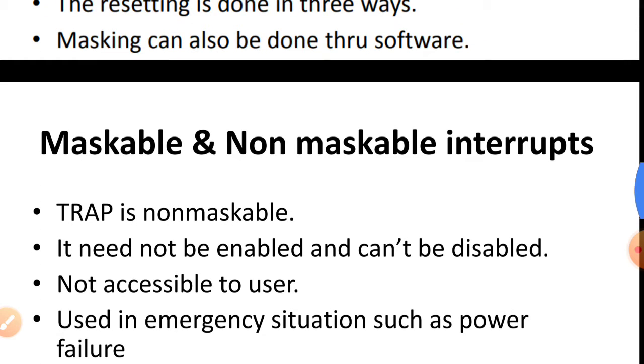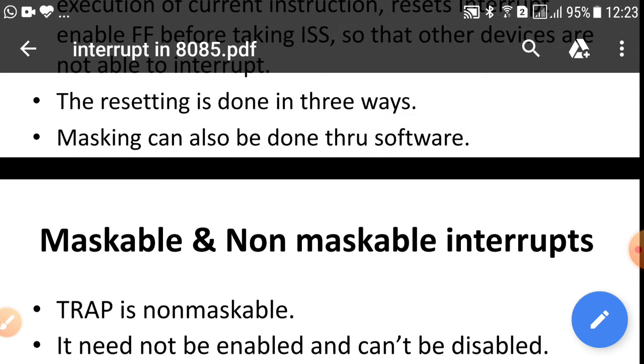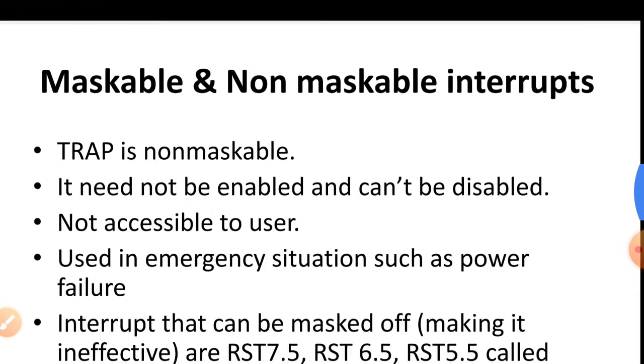Similarly, we can also do the masking process. Whenever one interrupt is being entertained, we can also mask the other interrupts, so that the rest of the peripheral devices which are connected to other interrupt lines cannot interrupt.